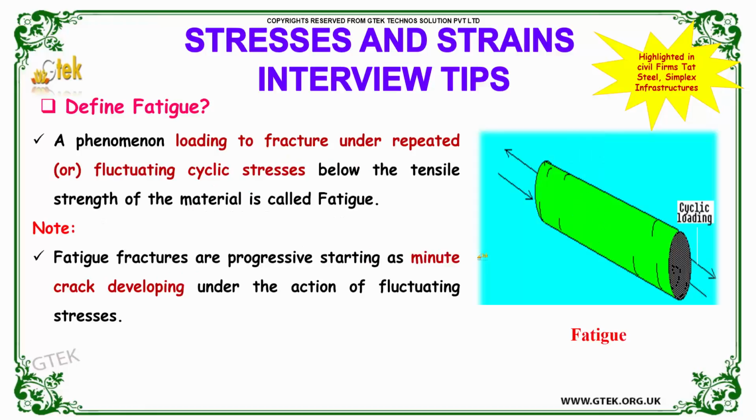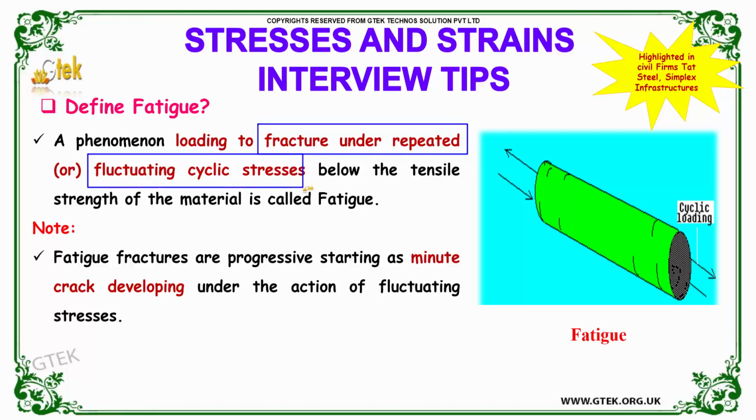Our next question is, define fatigue. Fatigue is a phenomenon leading to fracture under repeated or fluctuating cyclic stresses below the tensile strength of the material.